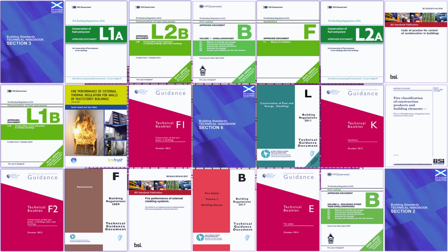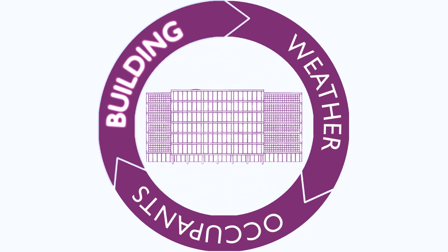While the specific details in these documents might vary a little, the principles behind the guidance and the recommended approaches are broadly similar. The first thing we need to consider is the type of building fabric we're dealing with. Concrete, steel and timber-based buildings all respond differently to moisture and contain different amounts of construction moisture which must be allowed to dry out. For example, buildings with a lot of in-situ concrete can take several years to fully dry out. This excess moisture load must be accounted for at the design stage.